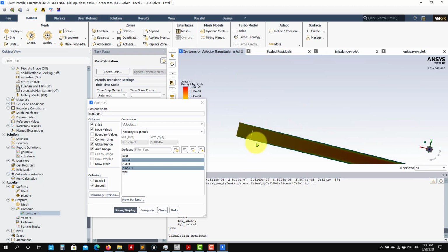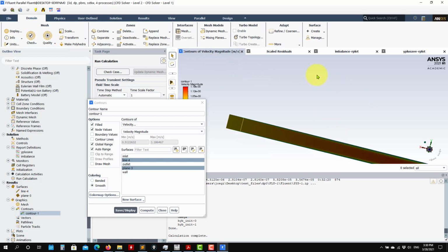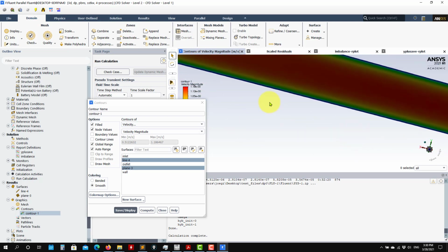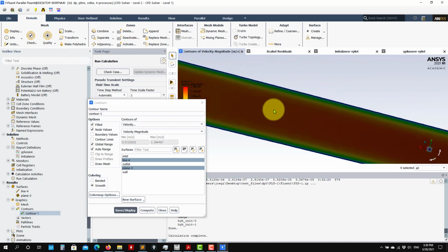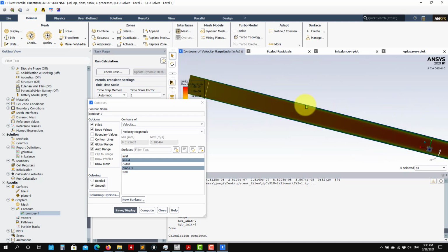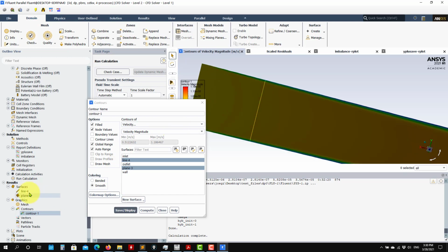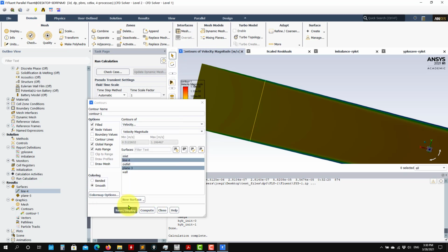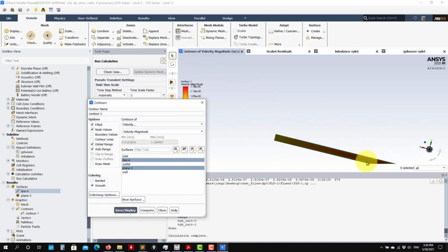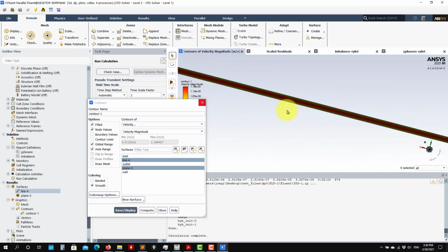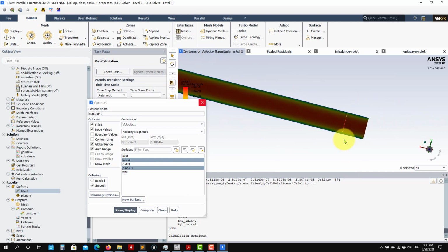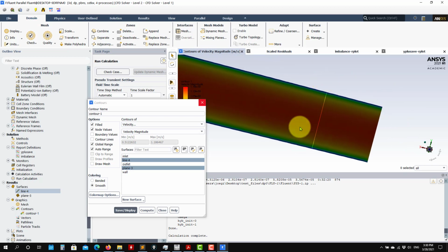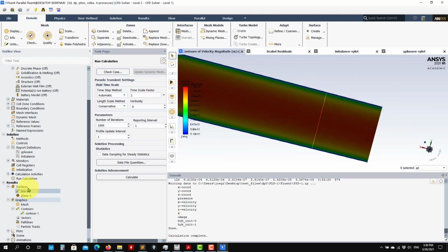Okay, but in this case, see, this is the importance of knowing your reference system, how you are orienting things. I put it here at the beginning where this is the inlet. I need to put it at the other extreme. So if I go back here, it should be 0, 1, 0, 0, 1. So close. So let me go here. See, this is important, how you set your reference system. So now I have it at the outlet. So this is okay. We have these two lines.